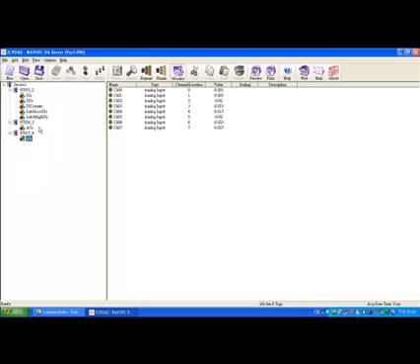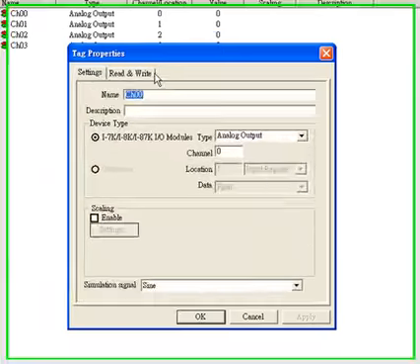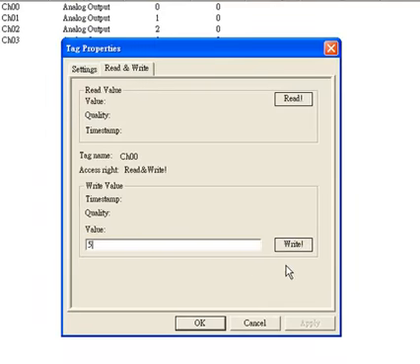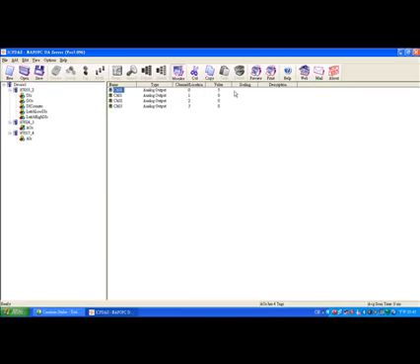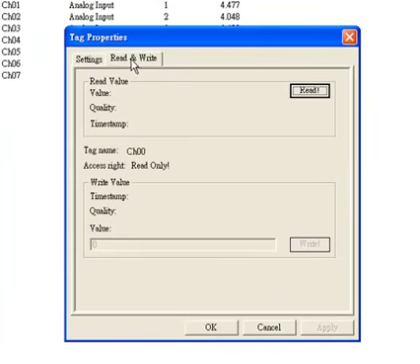We have linked the analog output of I-87024 with the analog input of I-87017. Now we can have a simple validation. Send 5 volts from analog output. The value of analog output shows 5. Now we change to the analog input. We can get the 5 volts in analog input from the analog output with Quicker.